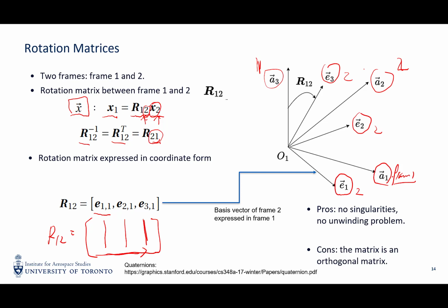And the desired lift direction is usually given by extracting the direction of the desired lift as a unit vector. So in this case, you have a unit vector rather than a series of Euler angles. But you can still do that. But if we have this relationship here, we can directly use the direction of the desired lift together with some other constraints by the heading angles to construct the desired attitude more conveniently.